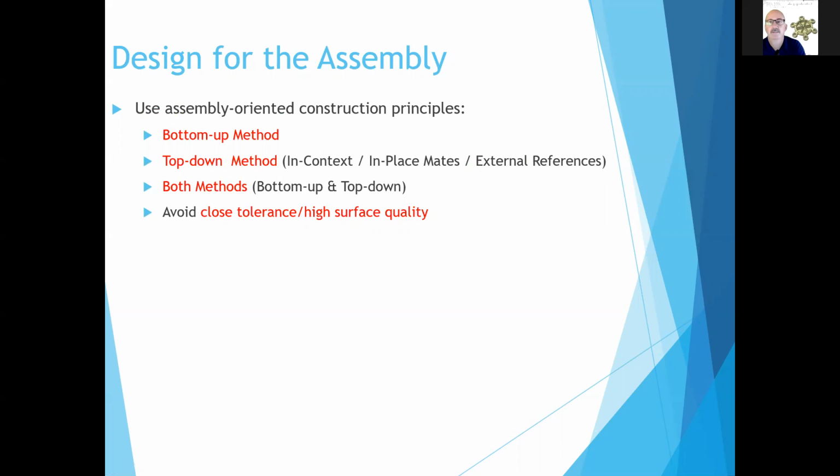There are two different methods. We're going to be using the bottom-up method, which is simpler than the top-down. Top-down is when you're taking a part and designing it as you're creating these little spin-off parts. That's how I used to do things when I was a senior design engineer for ITW. I'd make packaging machines and bring in some of the components, but then you'd have to design things like a sheet metal cover for a flywheel so that somebody wouldn't hurt themselves. You would create the drawing within the assembly and then export it out. That would be top-down or in-context modeling, and it's more complicated.